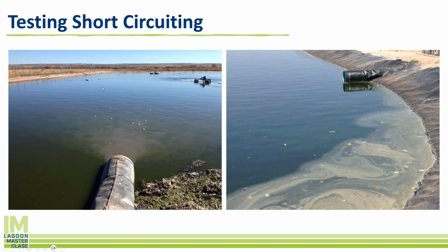They actually went straight and they skirted along the outside very quickly, moved over here and ended up within a matter of 24 or 48 hours right by the effluent. So what this showed the operator is that there's a flow or a current moving around all the aeration, around where the treatment is supposed to be happening, and beelining it for the effluent in 1 or 2 days, instead of it hanging out in this lagoon system for perhaps the design 10 or 20 days. So that gave the operator a clue that he needs to disrupt this channel right here to prevent the flow doing what it's doing in this lagoon.